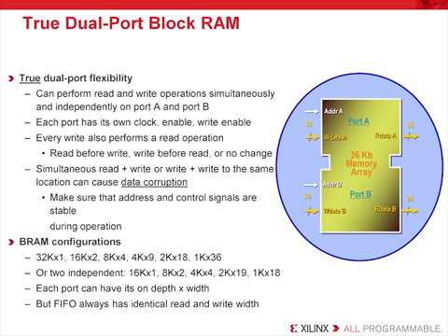Finally, there is a list of the supported block RAM configurations shown here. These will be chosen for you automatically when you use the core generator, such as customizing the memory size within the GUI. Each port can be customized to have its own depth and width, again giving it a great deal of flexibility to the user.